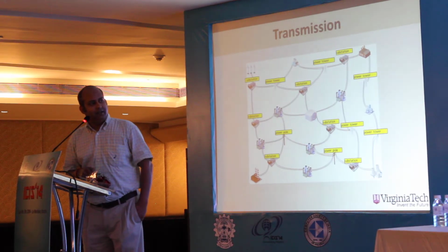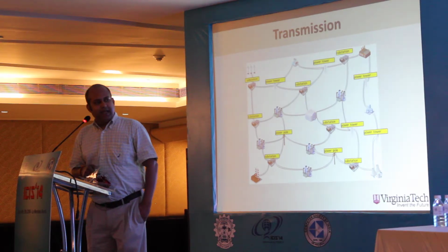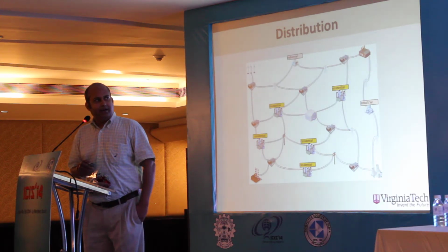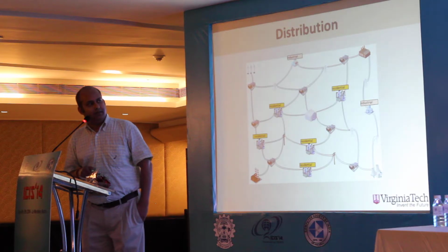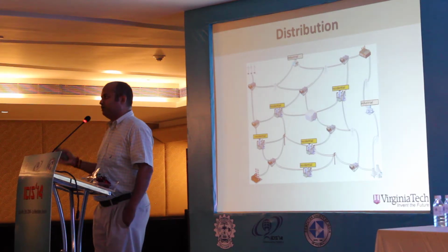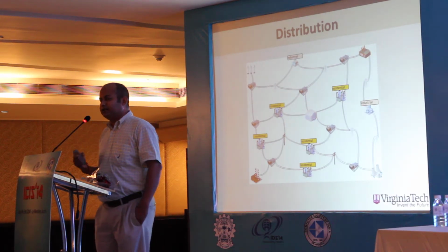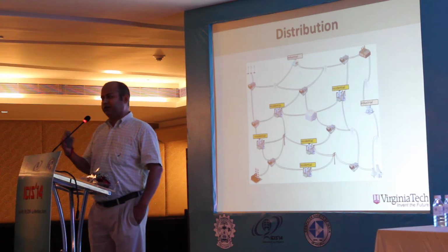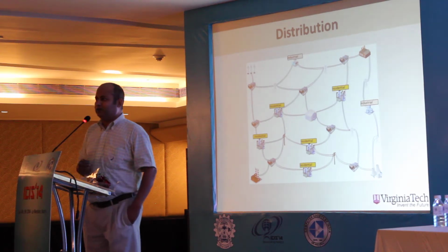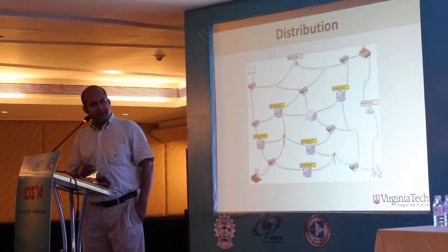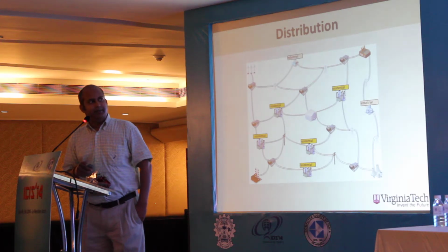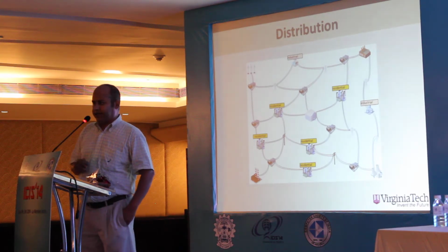And then you have power poles and so on. And eventually this comes to the city and population centers, where you have the distribution network, and the distribution network starts usually at the distribution substation. It goes to various transformers, because the transmission usually happens at a very high voltage, like 765 kilovolt or 440 kilovolt and so on and so forth. Whereas in the distribution, your home will be served at 220 volts, so therefore it has to be stepped down, so there will be a lot of transformers you will see on the side of the road and so on. So these are the three major components of a grid.